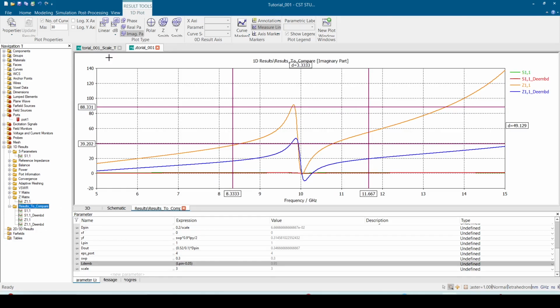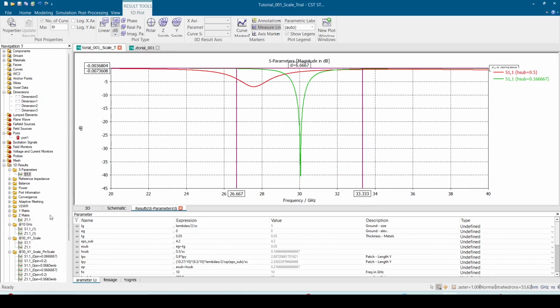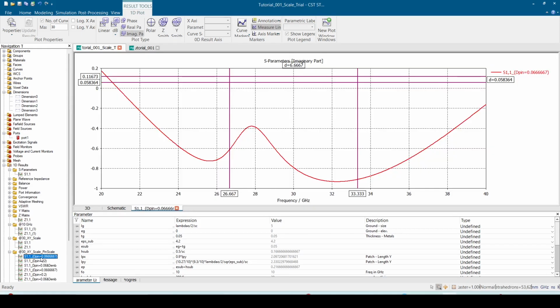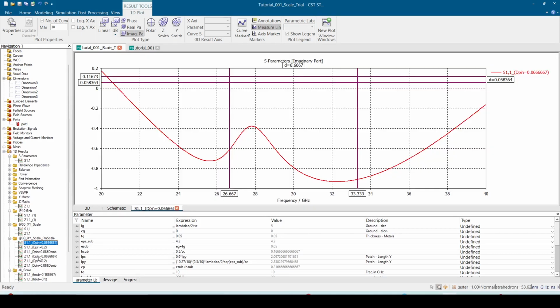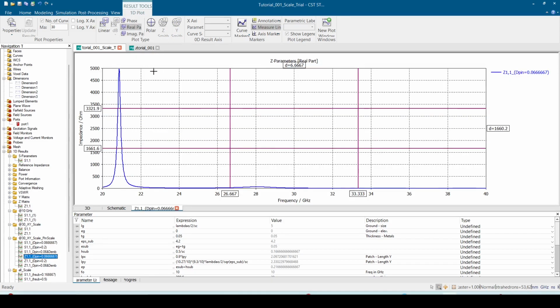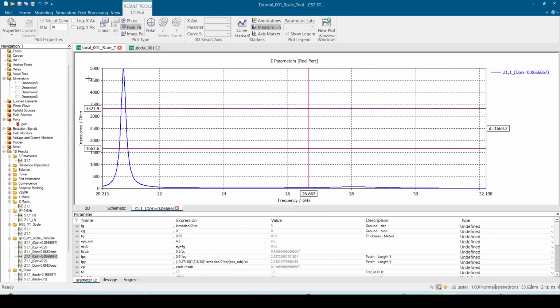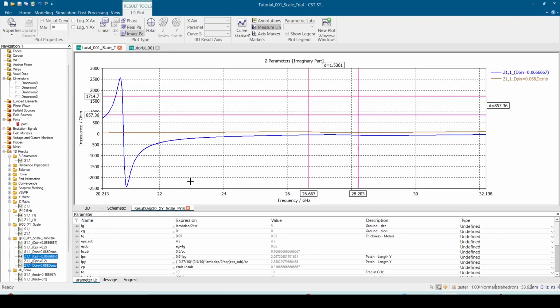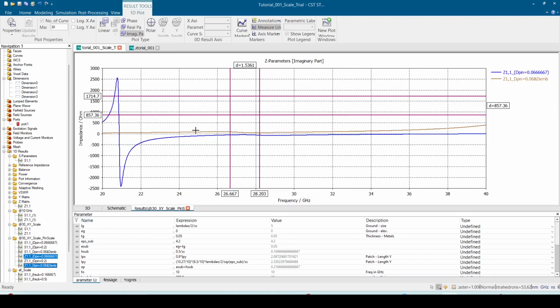And then when you de-embed, I did this exercise also. When I do the Z parameter, the small one, I have this mode which happens from the transmission line, because at some point it becomes 0, so there is the point when we have almost lambda over 4 of the transmission line length, and then it becomes infinity, right? If I just do the de-embedding, it starts to drag me to something else.